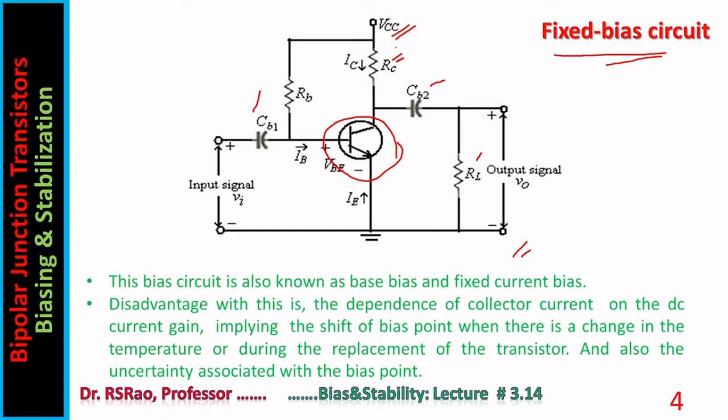Usually it is included in the circuit to provide certain amount of safety to the transistor against unexpected and high variations in VCC. VCC is supposed to be constant, but for one reason or other, VCC may vary. RC provides certain amount of protection against these variations. This protection is for the transistor.